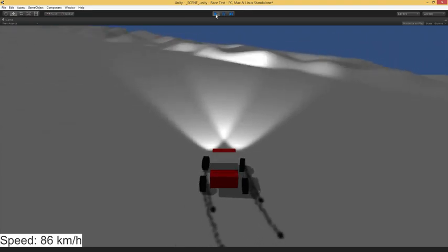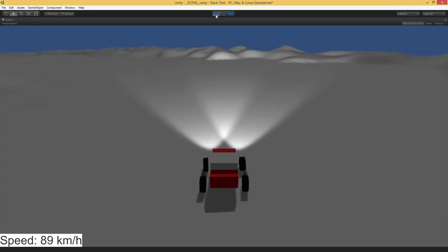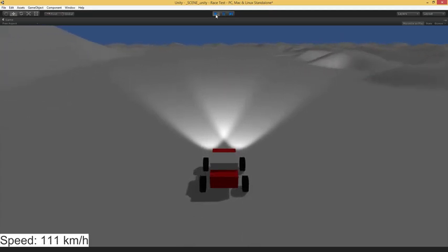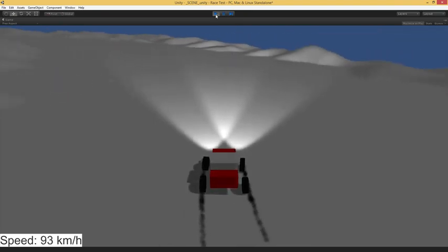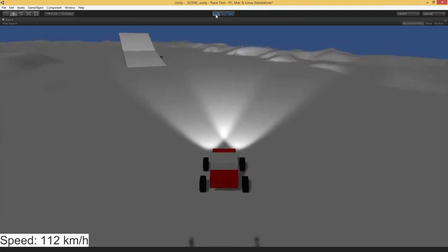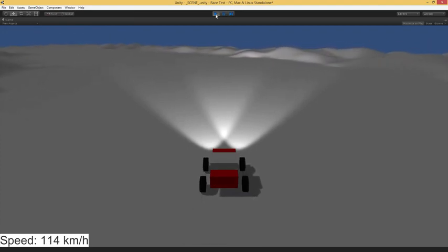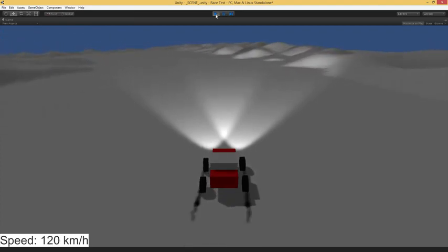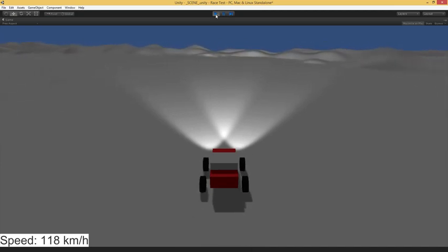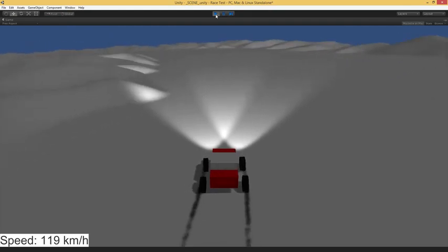And the reason real cars don't do it as much, partially it's the weight, and partially it's a better suspension setup, which we'll have to talk about here. Real cars actually have anti-roll bars, which effectively transfer force from one side of the car to the other to try to counter these rolls. And really advanced cars with super computerized suspension, the computers will be calculating these forces. An anti-roll bar is an actual mechanical thing, and in electronic computer-controlled situations, your computer can adjust your suspension settings on both sides to stiffen and weaken suspensions in response to a roll, to cancel out rolls and things like that.